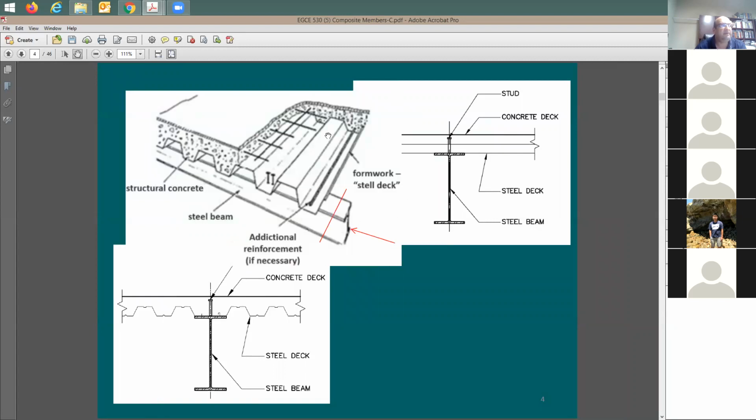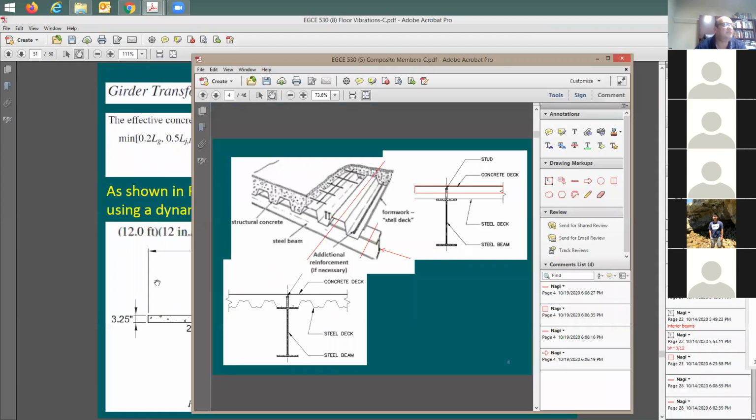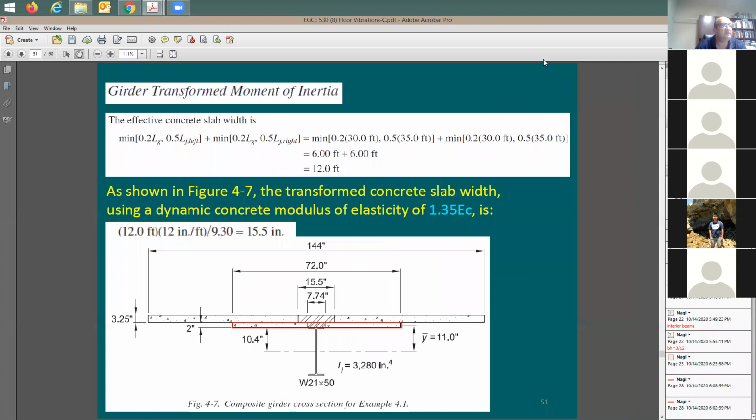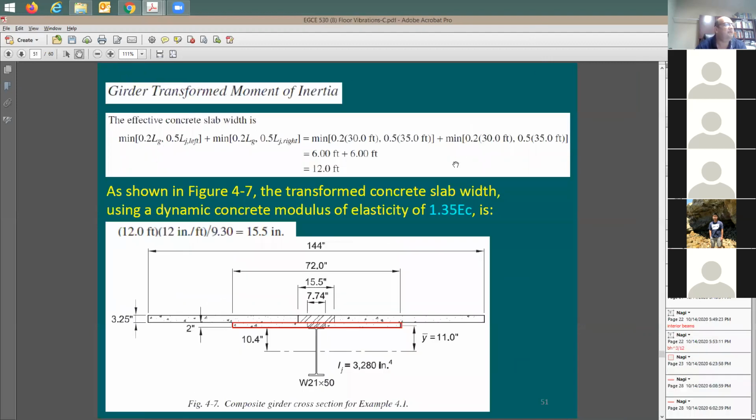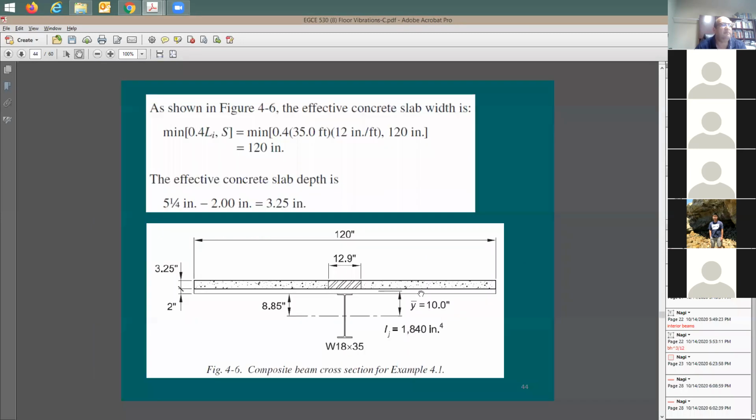correct? You see here, if you cut the section through this location, there's no concrete below the deck within here. And the concrete is gonna be only within this section. And this is exactly what we have in the beam analysis, right? So in the beam analysis, we don't have this piece at the bottom. So I said, okay, it makes sense. So in this case, it's gonna be the concrete, and here I have nothing, like what we have done in the beam analysis. If I may go back here and look at the beam analysis, right? Nothing on the bottom. Why?